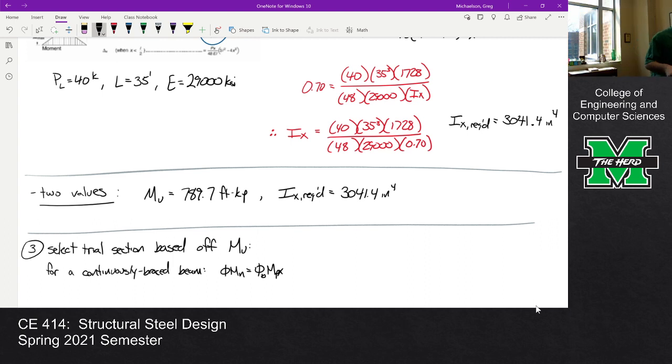Both Mr. Geis and Ms. Hudson selected within that group, but within that group, is that the lightest section? And you know what I mean by the lightest section, the second number. For instance, the one that Ms. Hudson put out weighs 136 pounds per foot. Mr. Geis's weighs 97 pounds per foot. So between those two, Mr. Geis's is lighter. But is there another section that's even lighter?